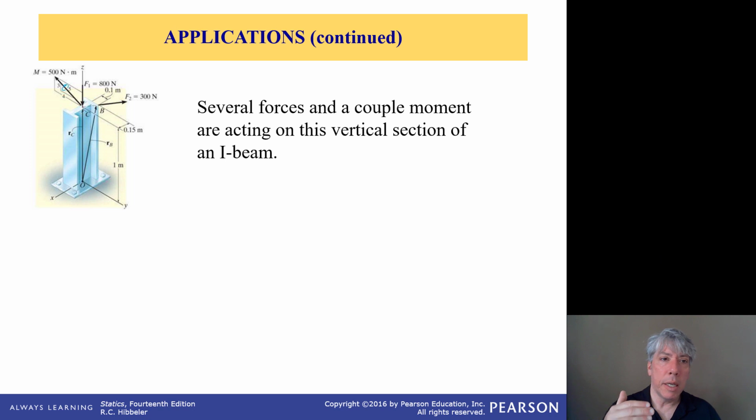Well, it's easier conceptually to basically think of removing the I-beam portion of the column and having some equivalent set of loads applied at O, at the plate itself, so that you can then move forward and determine the fastener size required to hold the plate down. So we need some equivalent set of loads at O that will do the same thing to the plate that this overall beam with the loads at the top of the beam are doing to the plate.